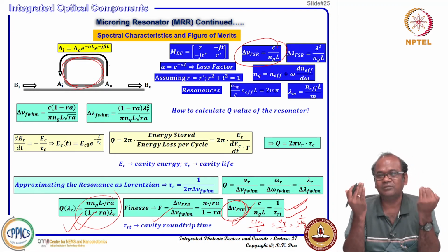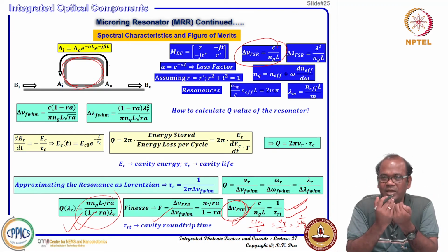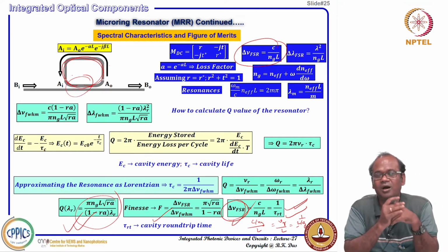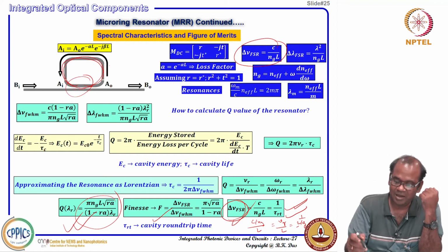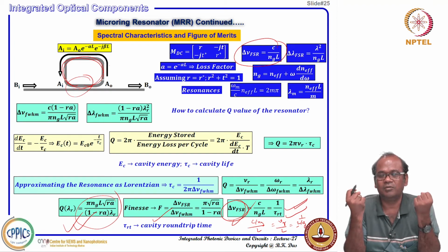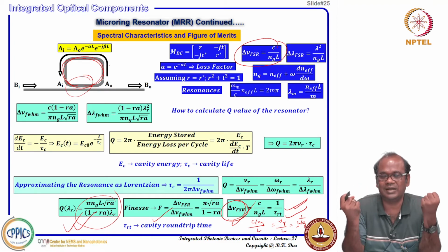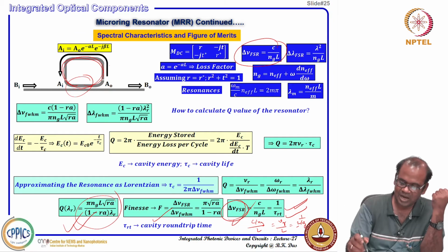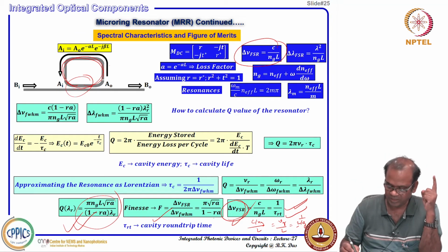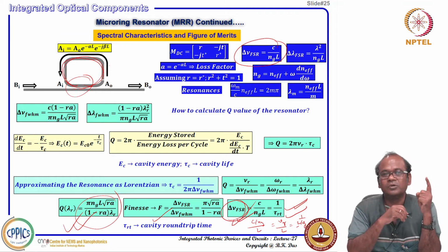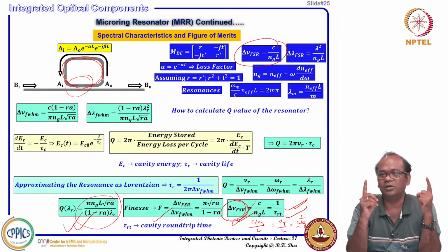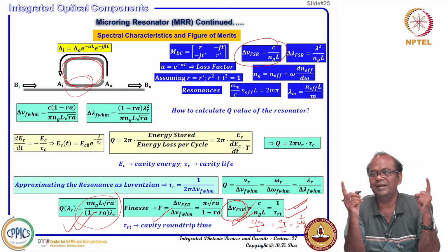So, now we can design whatever the value of R, whatever the value of A, R and A basically. That means the DC, the directional coupler, how you are designing, and A, what is the loss in the waveguide, that is actually responsible for storing more energy or less energy. But this R and T, they do not influence the free spectral range. Free spectral range is c by NG L, that depends alone on group index as well as length.